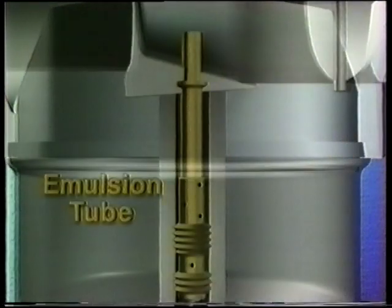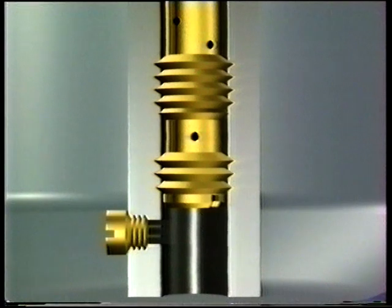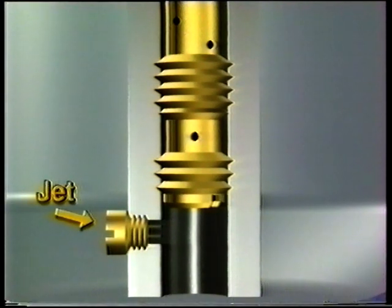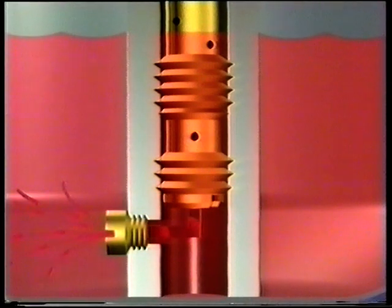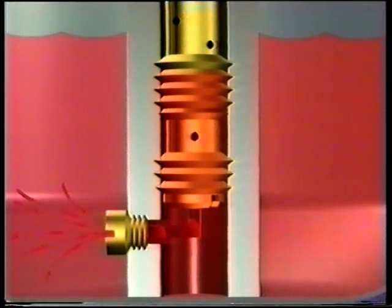Now, how does the fixed jet system actually work? An important component is the emulsion tube. This tube has a series of holes and a sealing area. It may also contain a jet or orifice. An important point to understand is that the jet limits the amount of fuel that is allowed to refill the emulsion tube when the engine is running. The fuel level in the emulsion tube varies based on engine load or throttle plate position. To understand how the emulsion tube works, let's look at 4 examples.